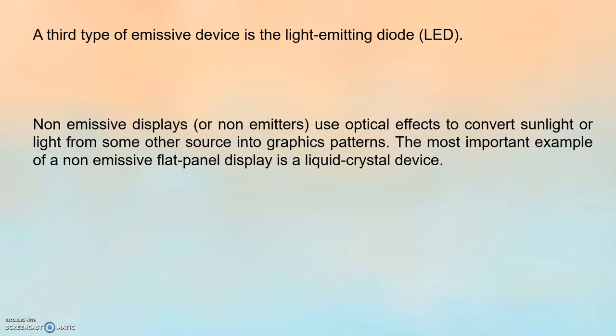The term liquid crystal is because these compounds have a crystalline arrangement of molecules, but they flow like liquid. These displays commonly use nematic liquid crystal compounds. Nematic means thread-like, and they tend to keep the long axis of rod-shaped molecules aligned.